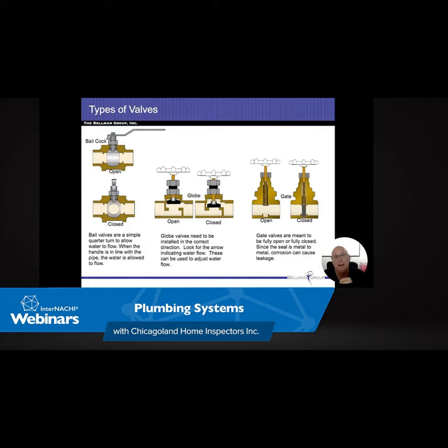But our biggest concern when we stack pipes here is these things sliding on top of each other. So what they do is they put a corrugated metal band around it with a rubber seal to keep it watertight, and then we put the compression clamps on it just so nothing can get away from it.